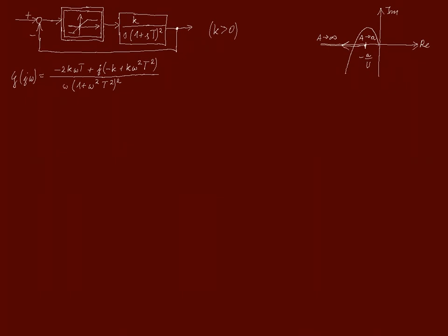Based on the task content, we want the closed-loop system to be always stable. Always stable, that means it is expected to be stable for any amplitude a. Therefore, the Nyquist characteristic cannot cover even a piece of the describing function inverse graph. In this task, one needs to find the range of gains for which both graphs will not intersect.